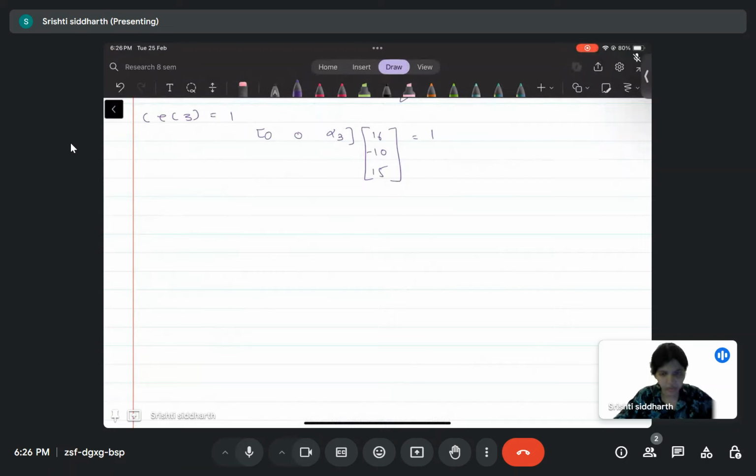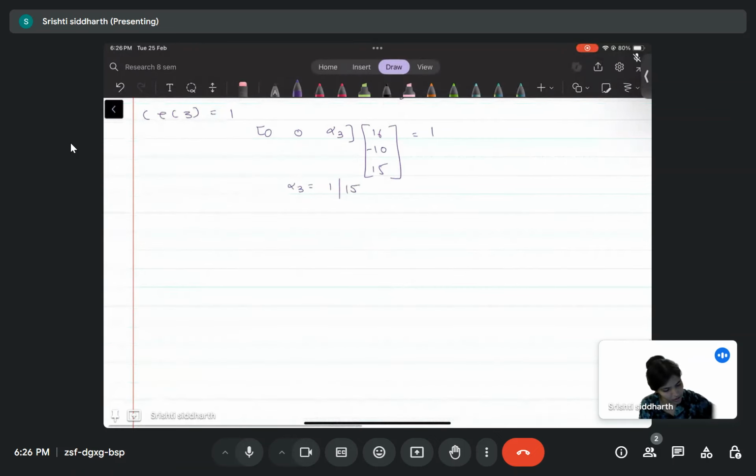So then in this case, what's the transformation matrix? It is C, CA, and CA squared. So now you can compute this. I'm going to write down the transformation matrix directly. Yeah, this is 0, 0, 1 by 15 as it is. Then we have C times A, which is minus 1 over 5, 1 over 15. Then we have 1, 1 and 1 over 15.